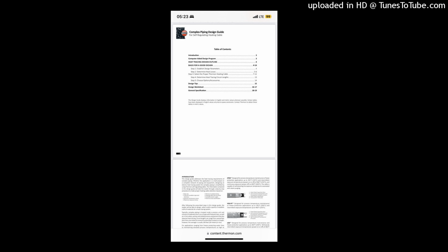Step 1. Establish design parameters. Collect relevant project data. A. Piping equipment: diameter, length, material. Temperature: low ambient, startup temperature, maintain temperature. High temperature limit excursions. Insulation: type, thickness, same size, oversized. Electrical: operating voltage, circuit breaker capacity, electrical area classification.